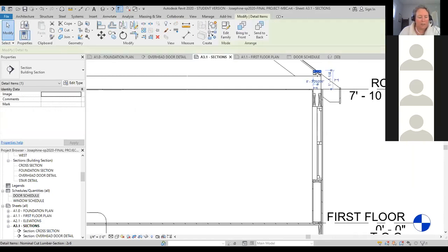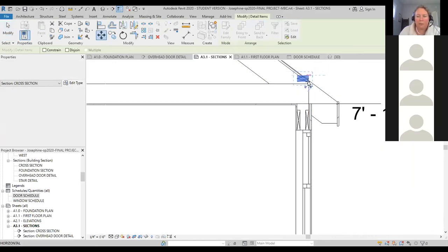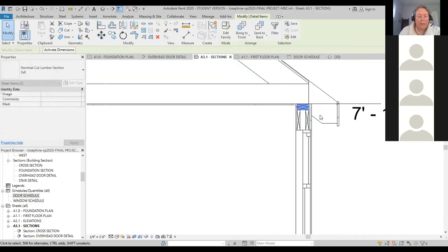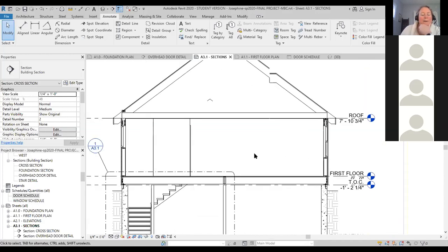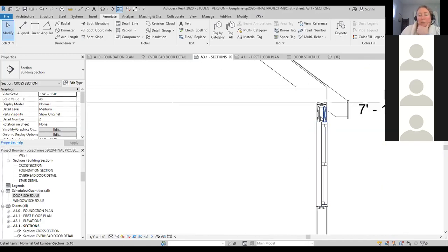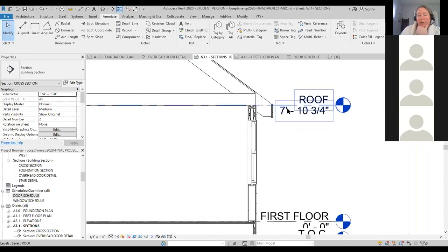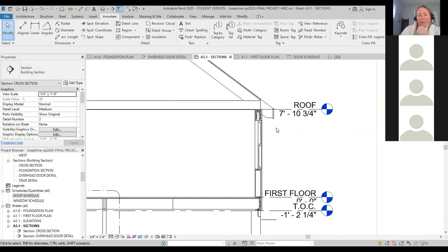because if I put all these things back where they're supposed to be, let's move this down here so the top plate's resting right on top of the 2 headers. That's the smallest wall height that I can have to fit what I need into my wall. Some of you might have 2x12s in here. If you have 2x12s, then your number would be 8 feet 0 3/4 inches when you add up those dimensions.